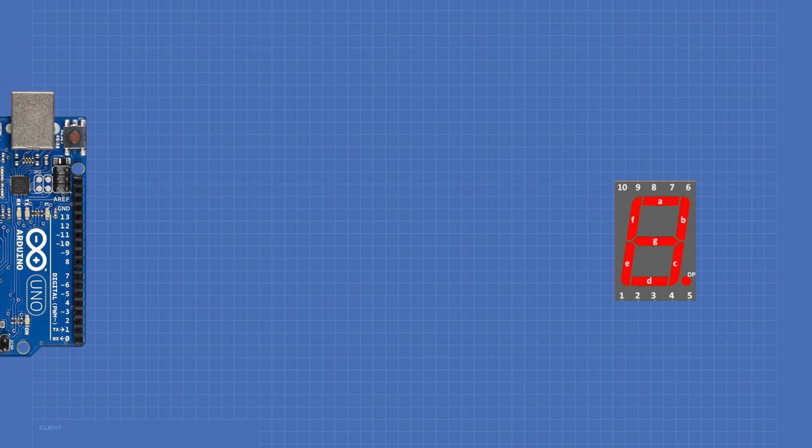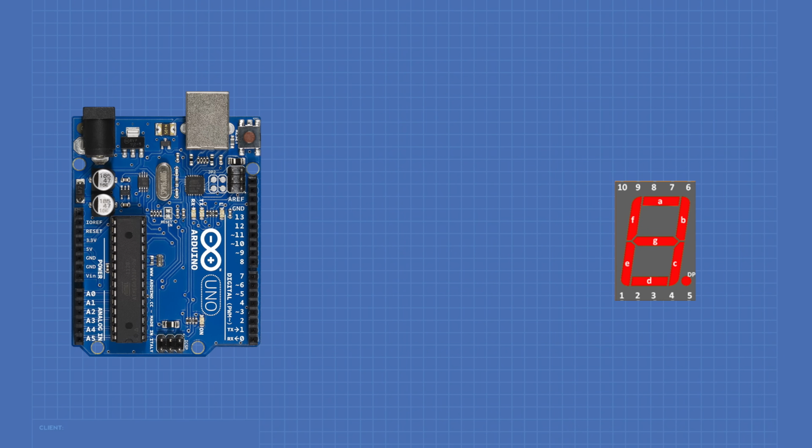In addition to the 7-segment LED, you're also going to require an Arduino Uno and 8 dropping resistors, 220 or 330 ohms. I used a resistor array pack which contains 8 resistors in a 16-pin DIP package because I find it a lot easier to wire with this, but you can also use individual resistors if you wish.